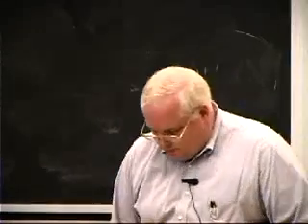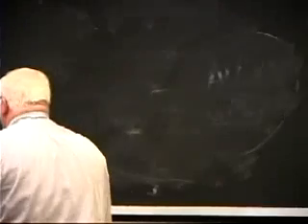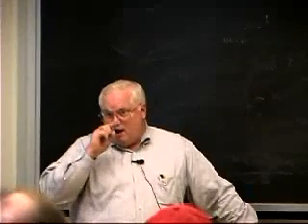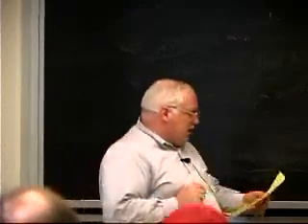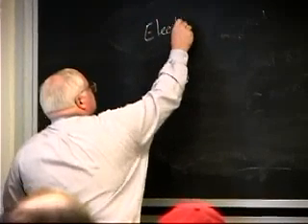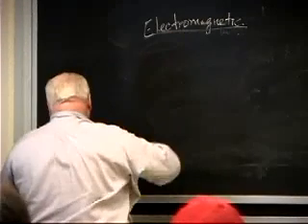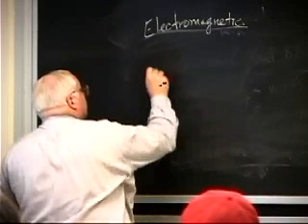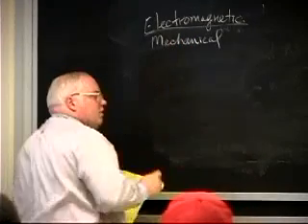let's see how much time I'm going to have here. If I want to do non-destructive testing, I'm going to have to find these flaws that we were talking about. I have to have energy interact with matter in some way. So I can start on the highest level of abstraction here. I can have electromagnetic energy, which is all the way from radio waves to X-rays with light in between. I can have mechanical, which is acoustic emission or ultrasonics where I'm vibrating it.